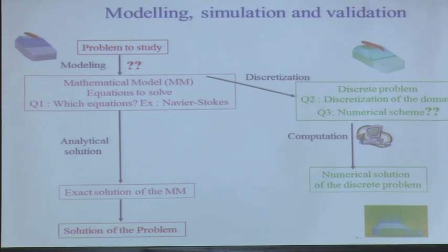This is the model we want to solve, and we believe it is a good approximation, a good prediction of the real flow. In some way, you may think it's not correct, because, for example, if you take the Navier-Stokes equation for incompressible fluid, and then you increase the velocity, at some point you will see compressible effects in reality. But if your model doesn't contain this effect, you will solve it maybe properly, but you will not get the right physics. So you have to take care about the model you solve. If you want to compare to an experiment, you have to be sure that both of them are adequate.